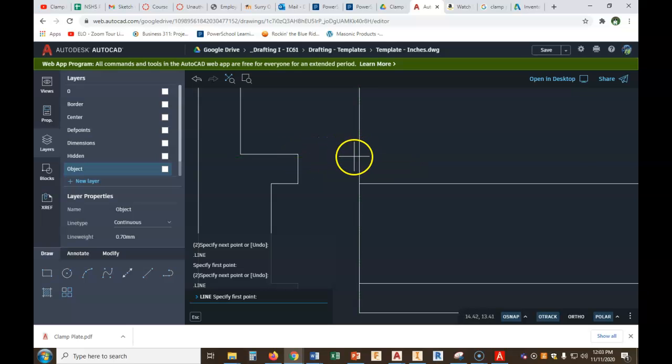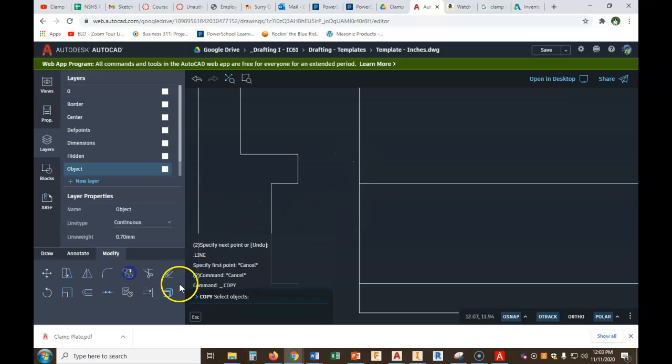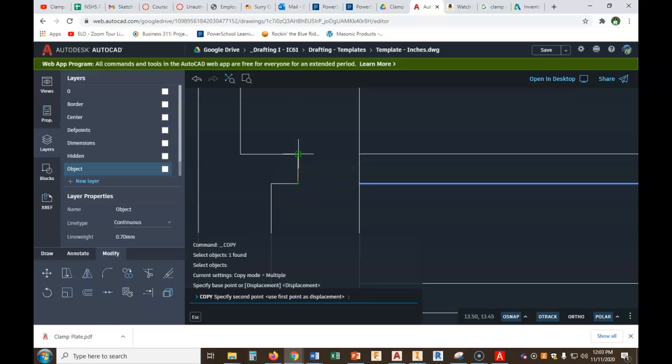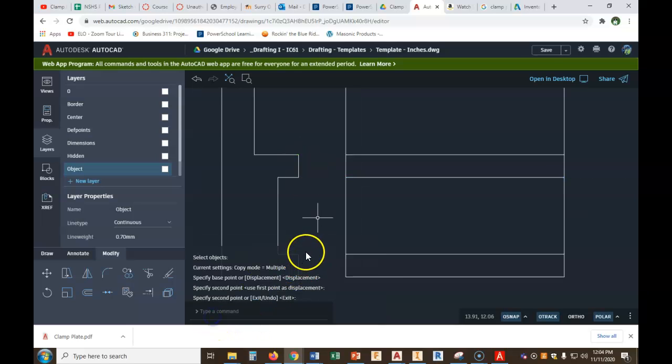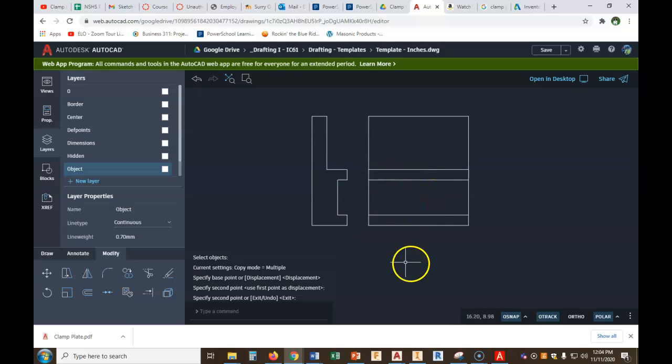And if it's not giving it to you, maybe you're worried about it. This may be where you want to go to modify, say copy. Pick this object to copy. Now hit enter and say confirm, or say confirm selection down here. Now specify base point. Look, we know that lines up with that, so click here. Now where do you want to move it to? Here at this height. Okay? And then say confirm. So if it won't do it, if it wants to jump to the wrong point, that's the easy way to fix that. Okay? So there, look, there's that shape. There's our 4 rectangles.